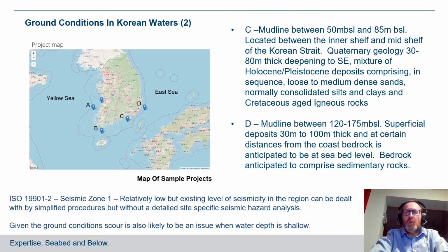Just in terms of thinking about other ground-related issues, there is a relatively low but existing level of seismicity in the region. Although this is defined as seismic zone 1 in the ISO standard, so will not require a detailed site-specific hazard assessment.